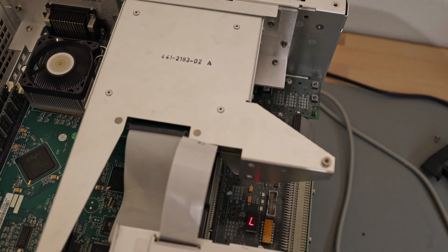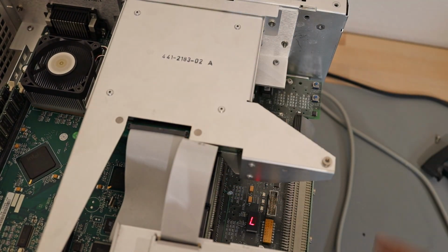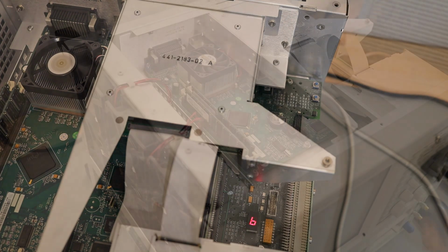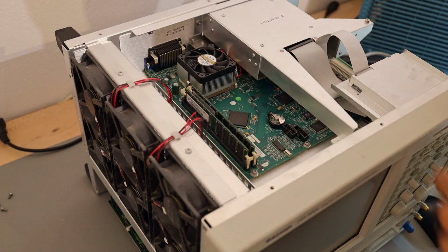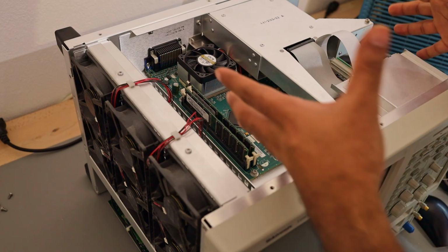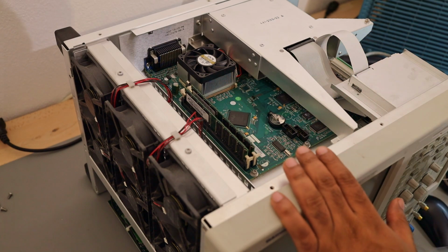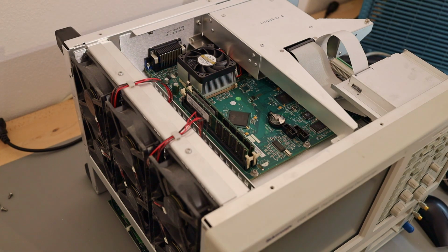It will keep repeating. There is a memory, I'll show you in a second. I have to take out this board to reach that memory, and we will try to fix that memory as well. Maybe we'll need to replace the memory, or we just need to replace the power itself. This CMOS battery I have replaced, and to be able to access the VxWorks configuration memory which is on the VxWorks board, I need to take out this whole motherboard. For that I need to take out a few screws. It's a similar process. Let's do it as well.